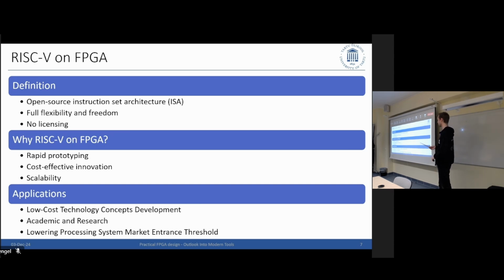And that's also where FPGA plays a big role: if I can prove my system on an FPGA and I can make an FPGA reliable, I may get the resources or the funding to put what I have tested into actual silicon, into an ASIC tape out. Then I have a lot of R&D and money saved, and I already have a proof of concept, and I can say, this is what I get on FPGA. If I have an ASIC with this technology, I'm going to get this much more performance.